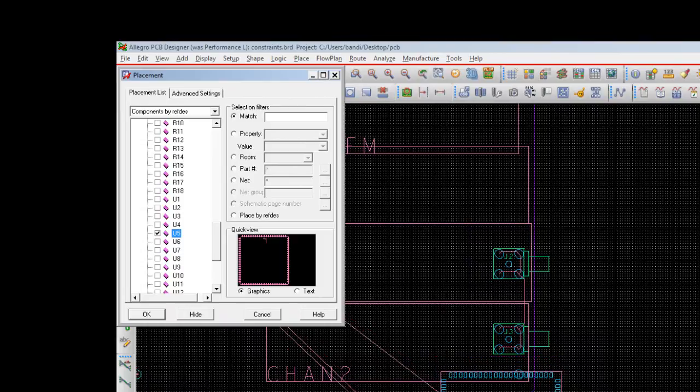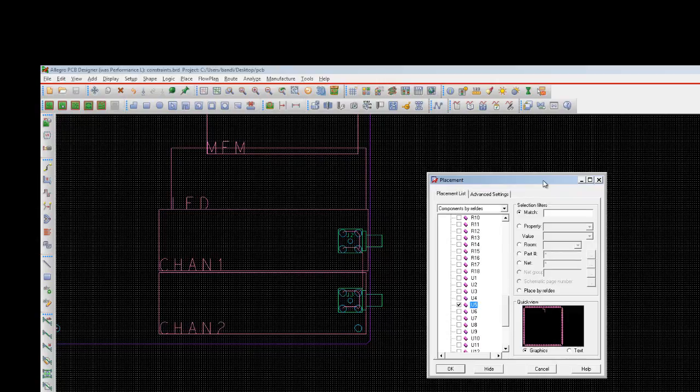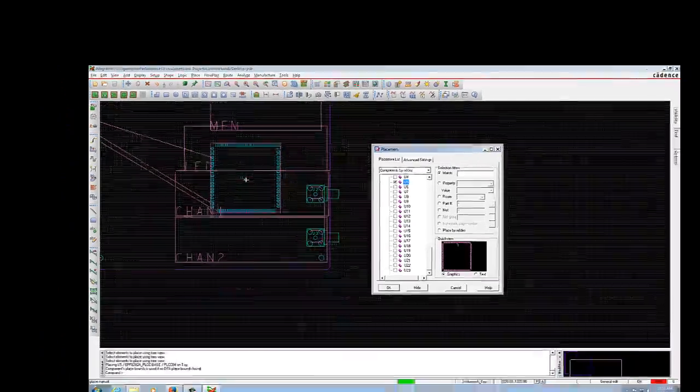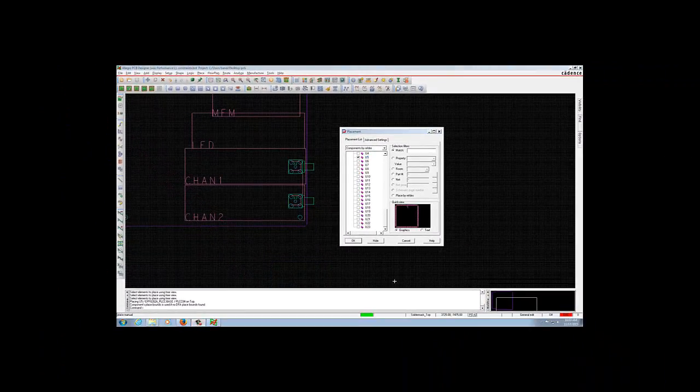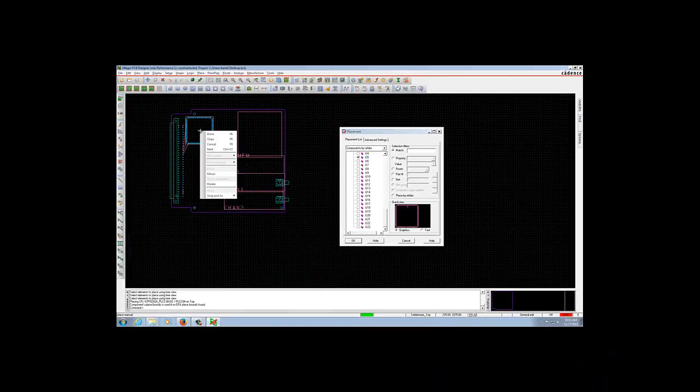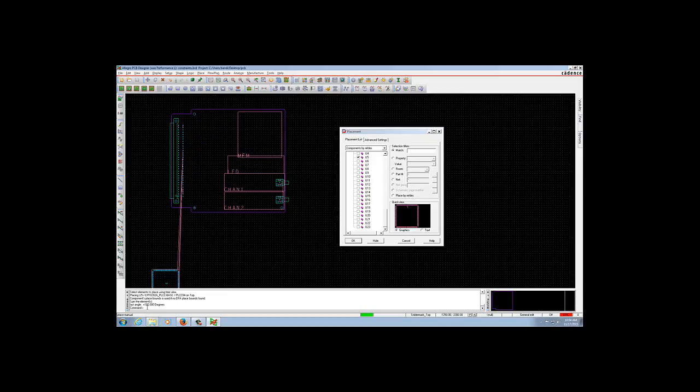You should rotate the U5 to 180 degrees by right clicking and selecting the rotate option. You can see U5 is attached to the cursor. Select rotate and then rotate to 180 degrees and just click on it, and again click on it to place it on the board. You can see 180 degrees in the commander window.